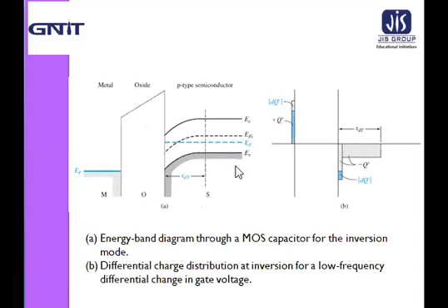For this inversion charge that responds to the change in the capacitor voltage, the capacitance will be the same as the oxide capacitance, that is COX.